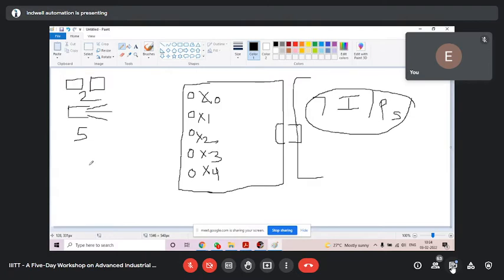See, we cannot do anything. If we have a sensor, we will have to connect it to a terminal. There is no other option. A sensor is an automatic input. It is not operated by man. So this must be connected to a PLC terminal. But if you have manual switches, meaning the switches operated by a man, an operator, like push button, selector switch, rotary switch. These are manual switches. If we have an HMI, manual switches we can ignore. Listen, if we have an HMI in our project, manual switches we can replace. So these two push buttons you are not going to use.